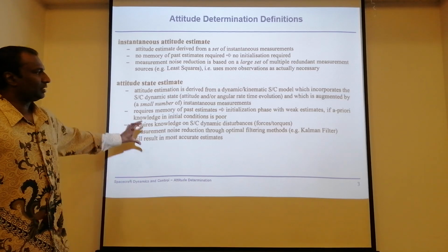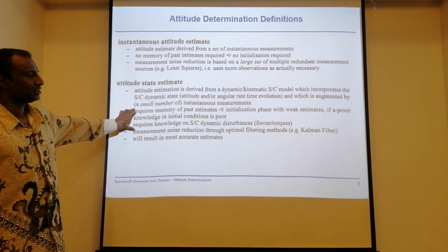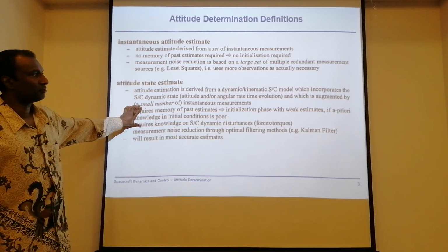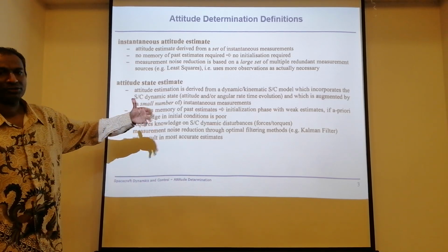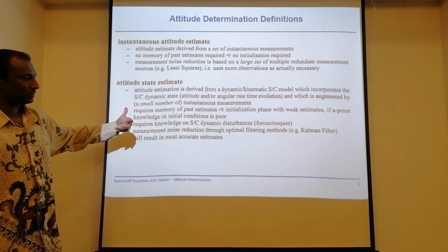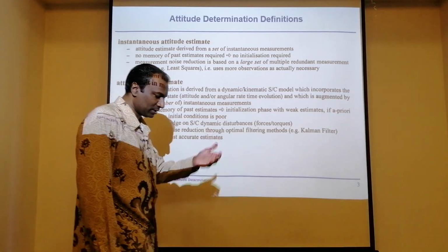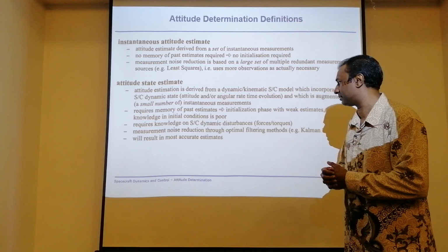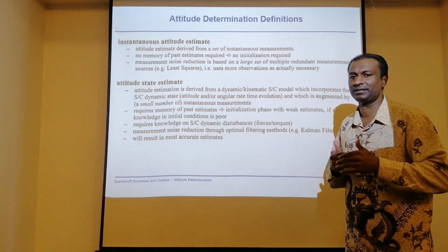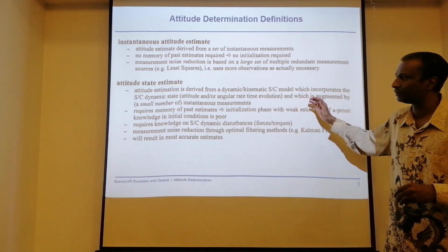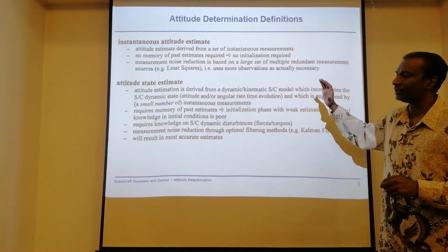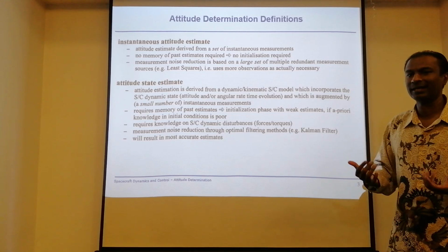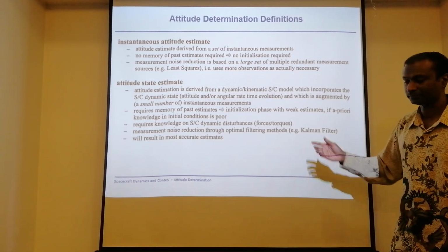So if you can see, the accuracy might not be very good in that sense, the reason being that a lot of estimation processes are there. Typically, most of the algorithms you will use are filters like Kalman or even unscented Kalman filter, basically to get your actual estimation. So there are processes to run. But for bachelor level, I think you just need to know the difference, basically how you can get a 2-axis attitude determination and how to do a 3-axis attitude determination with a combination of sensors.